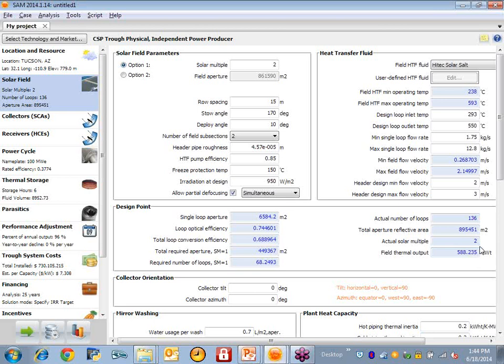In a way, we're just adding additional energy into the loop to increase the temperature further. So it doesn't necessarily matter what the collector geometry is in that case. It's more that we are able to add more energy than we lose in thermal losses at these higher temperatures, and so the more collectors you add, or conversely, the more you slow down the flow rate through the loop, those higher temperatures will be attainable.